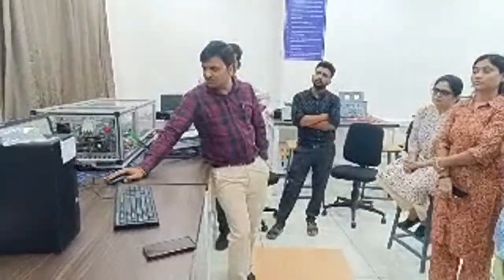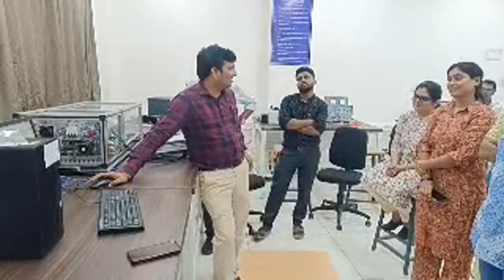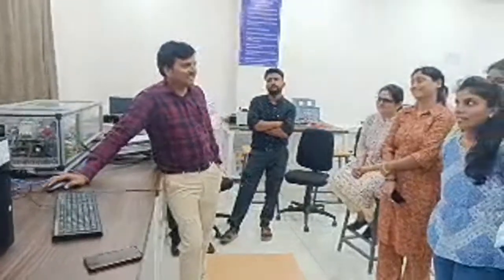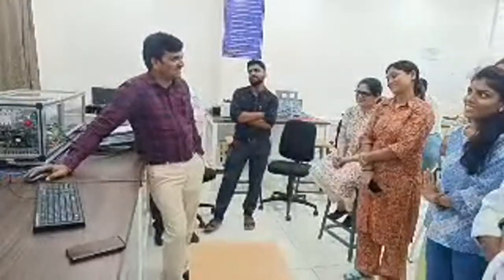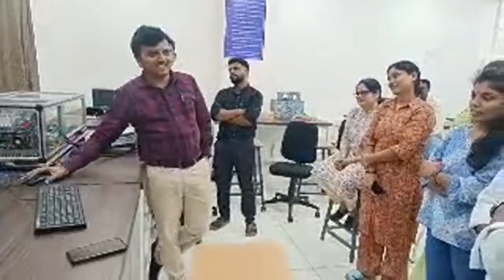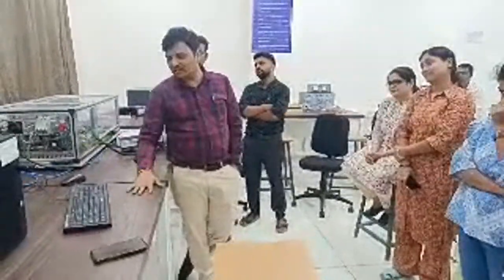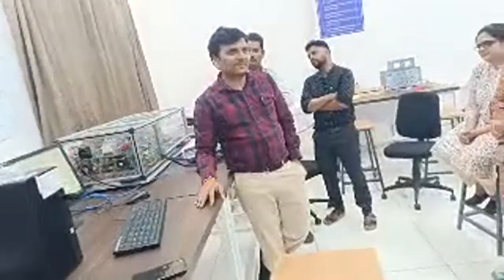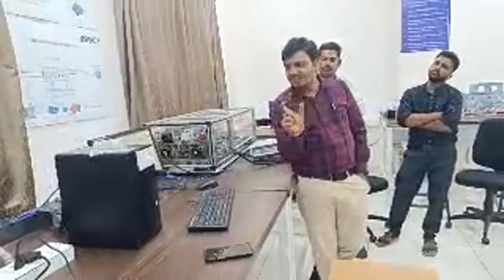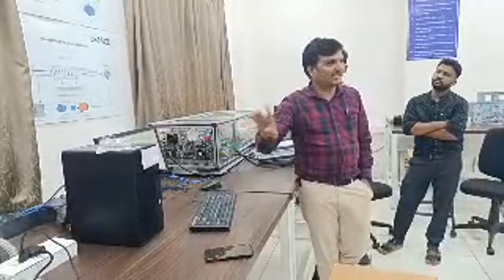You can generate your GUI, graphical user interface, as best as you can, depending on how good a designer you are. So you can design your GUI. We are very poor in design as electrical engineers, but you can design your best GUIs, and how beautifully electrical machines are, you can design. Here I designed a numerical input instrument and connected this variable to it. Now my period of pulse variable is connected to that, and I can change it by entering the value.